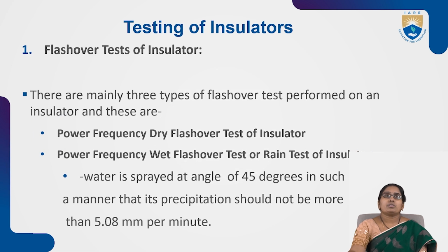Flashover test. So what is this flashover test? In this they apply voltage to the insulator and they will see the voltage at which we will get the flashover, the voltage at which we will get an arc through the insulator. Under this there are three types of flashover test.